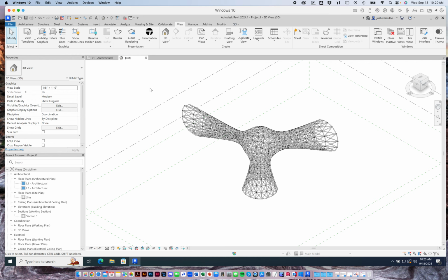Right? So we can do that several ways. First, we can start to give center lines for this grid. Then we can start to place components like columns and beams along those center lines. And what's nice is when you draw the center lines first, you draw the levels, then when you start to draw the columns and beams, they're connected to the column grid. So as you start to move the column grid, all the columns and beams start to update, right?